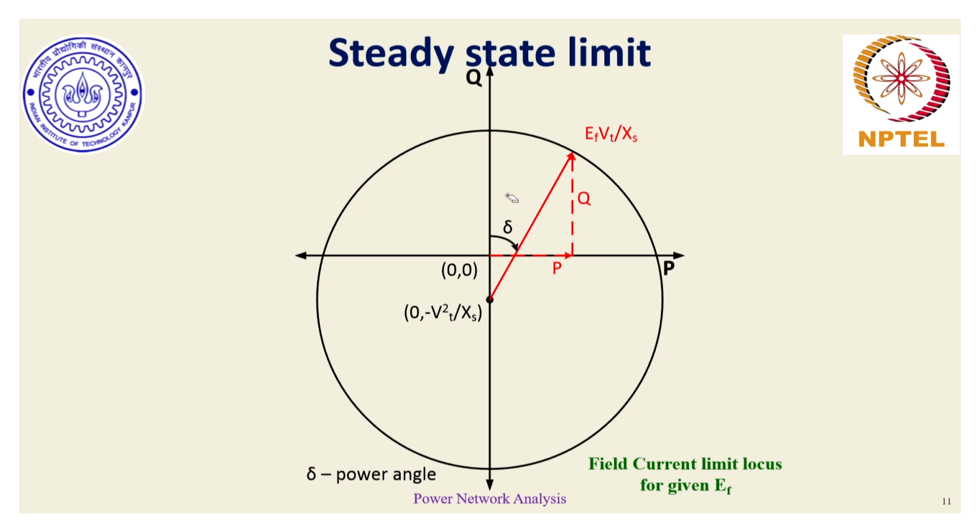So now if the load angle is the angle of the radius with respect to the reactive power axis, delta equal to 90 degrees would essentially mean, in the generating mode, that this radius has rotated and the angle now being formed is equal to 90 degrees with respect to the Q axis, and probably this is the line which is the maximum steady state real power which can be delivered by the machine in generating mode.